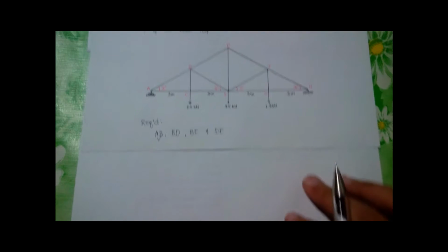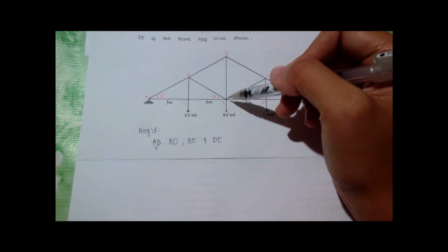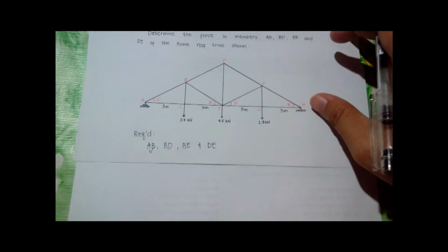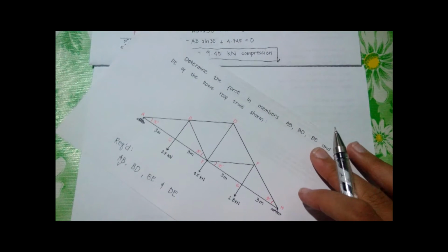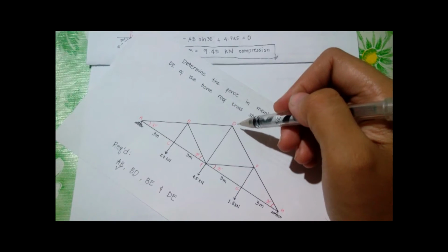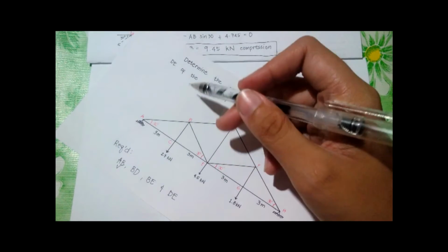Next, let's now solve forces at joint B, and this includes members AB, BD, BC, and BE. So here, to let us solve the equation easily, we could rotate the given figure like this, and let's have AD as our x-axis for our free body diagram at joint B, and of course the perpendicular of it as our y-axis.